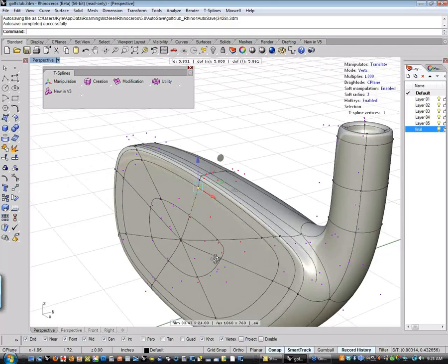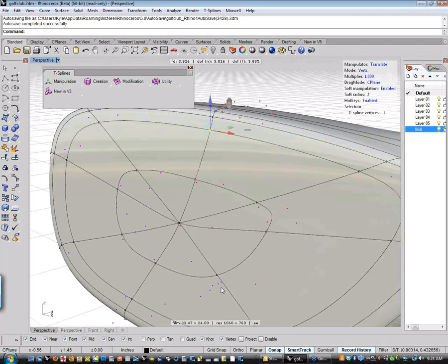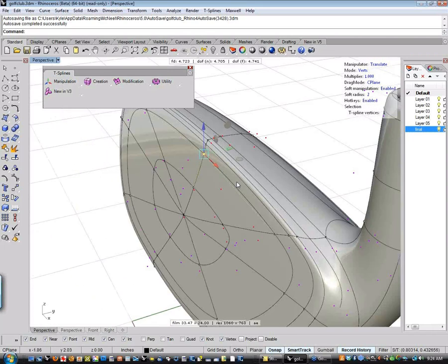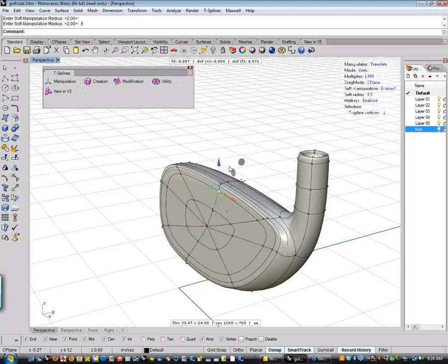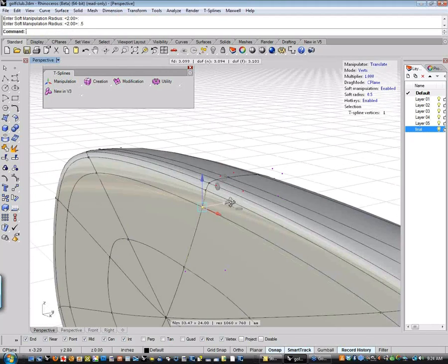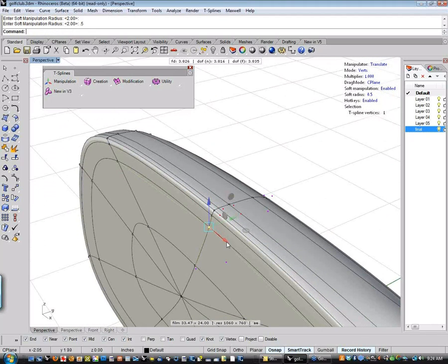And you'll notice, I don't know if you can see on this webinar or not, but the dots change color as they go. They're bright red here, they start getting a little more purple, and then they're purple out here. That is affected by the radius. If I change this radius to, say, 0.5, you'll notice that my area of influence has dropped considerably, so now my red dots are in here and it fades out more quickly.